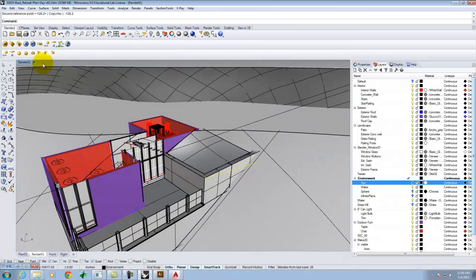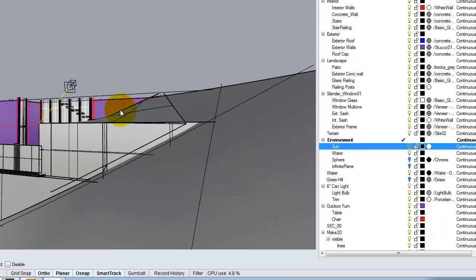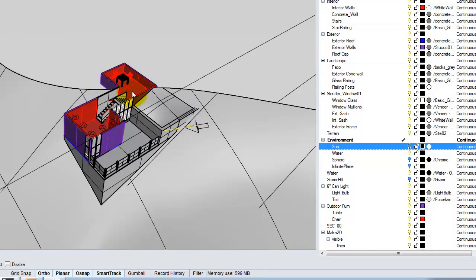Right? So now when I go to the basic directional light here, I can just snap to that line. So there, and I have a directional light that exactly matches my sun. Right? But it's much less intense. So instead of messing with the sun settings and whatever, I can use this to my advantage. Okay? So there it is.